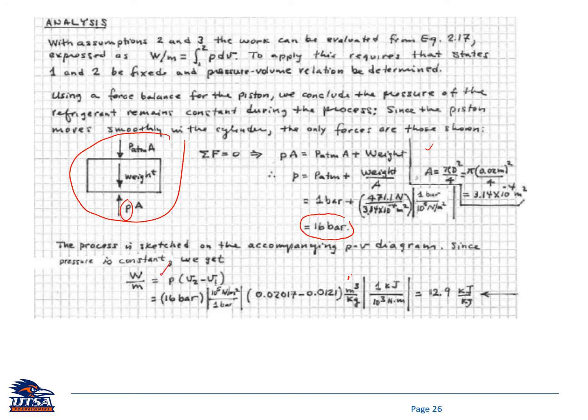you know the pressure, and so it's constant pressure. It's constant pressure, and then state 2 has the same pressure as state 1, and then temperature is given. Then you use table A4 to get what is V2. Okay, V1 you get it from table A3 at the 16 bar. Then you plug in all numbers, then you should be able to get the work there. So P times dV there.